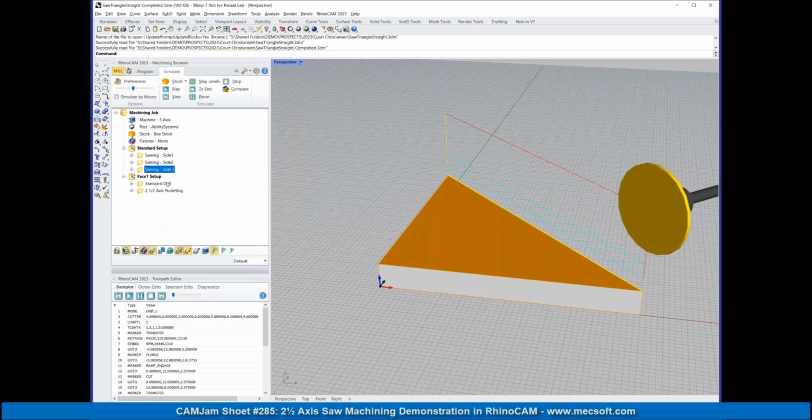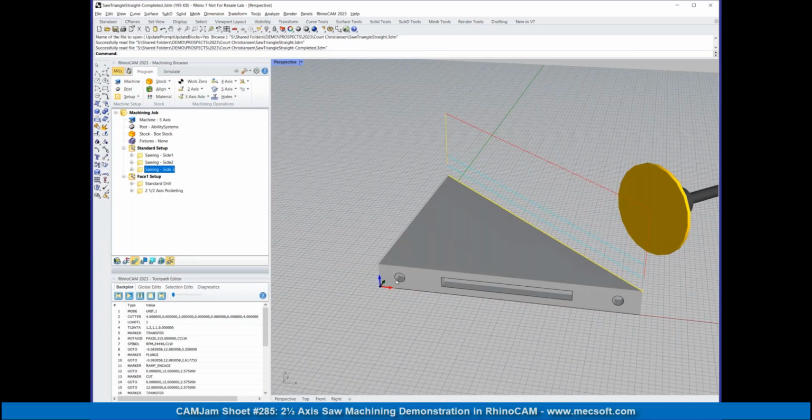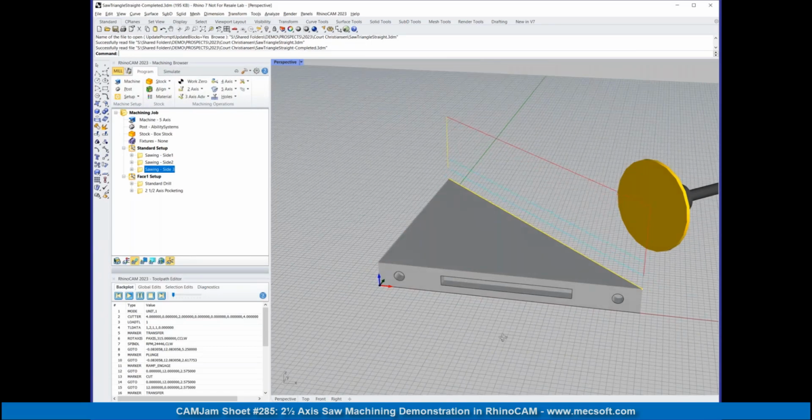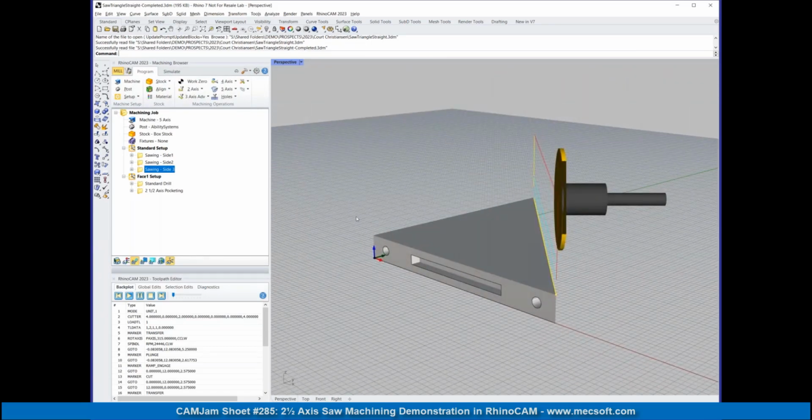As far as the aggregate machining, let's say we wanted to machine this pocket and these 2 drill holes on the side. This is where it gets a little more complicated. You need to create something called a setup. The setup is basically telling the system which way the tool is oriented. In the case of an aggregate head, you would probably rotate it by 90 degrees to come normal to this surface. That's what I've done here.